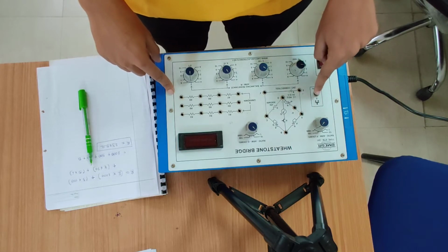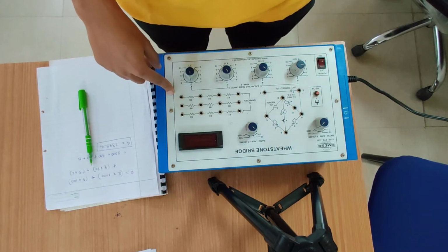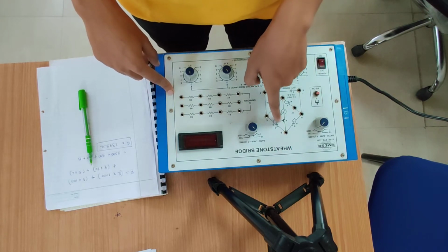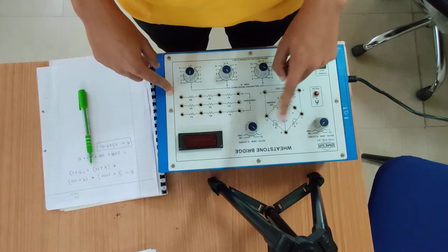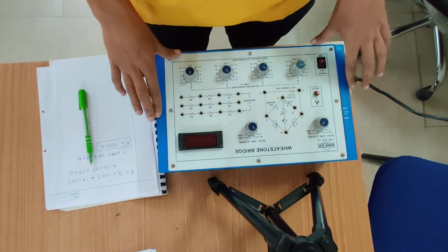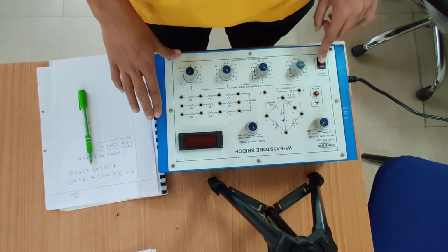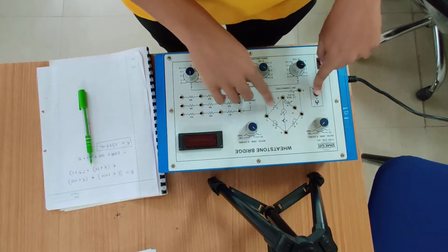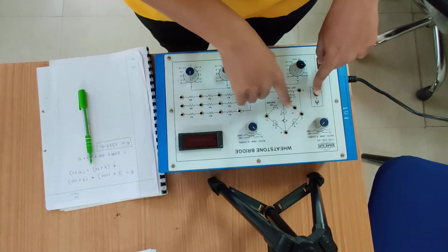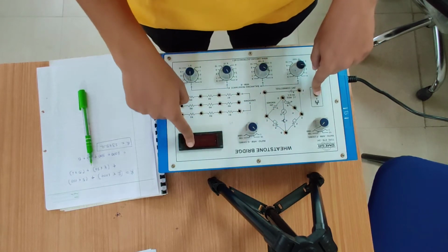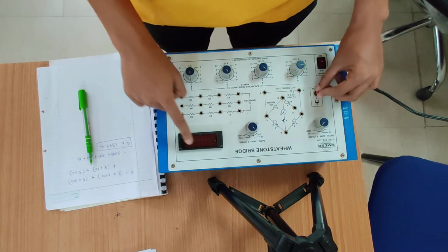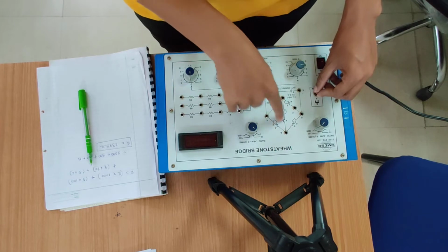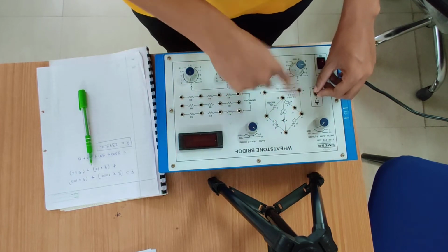Whenever I push it, it will be on. If I release it, it will be off. See, that push button switch is here. Whenever I connect this circuit to the power supply and turn on the power, if I don't push this switch, then the galvanometer would not be connected into the circuit and the indication would always be 0. So without this switch, the galvanometer indication would always be null, meaning 0 value, because it is not connected to the path B and D.